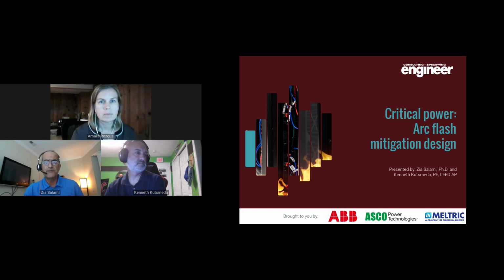Minimum and maximum short circuit current injecting into the facility, voltage variation, and the type of equipment: is it switchgear, MCC? That is really important, because defining the type of gear, whether it is a panel, switchgear, MCC, or cable, has a real impact on the short circuit and the arc flash study.